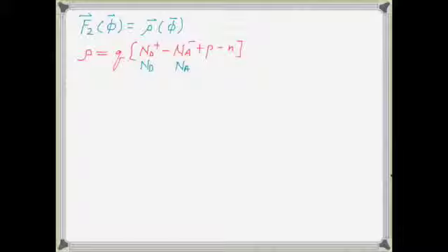And so all I need is the derivatives of p and n with respect to phi. So I'm going to need negative q dn_i/dphi_j and q dp_i/dphi_j. That's what I'm going to need, or some approximation to those.